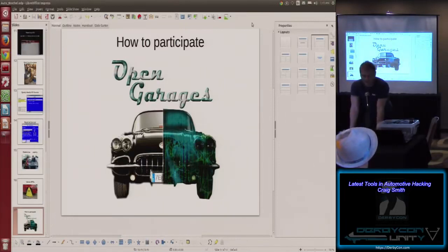Oh, you're talking about the security access token? Okay, so the password piece that I was referring to that has the keys to the other car are these security access tokens. Typically when you're going to modify firmware, like say change your VIN number, which you can do, you just need to do this challenge response. You make a request, 2 to 4 bytes usually come back, and you have to give it an equivalent 2 or 4 bytes that's valid, like a rolling key typically or something of that nature.